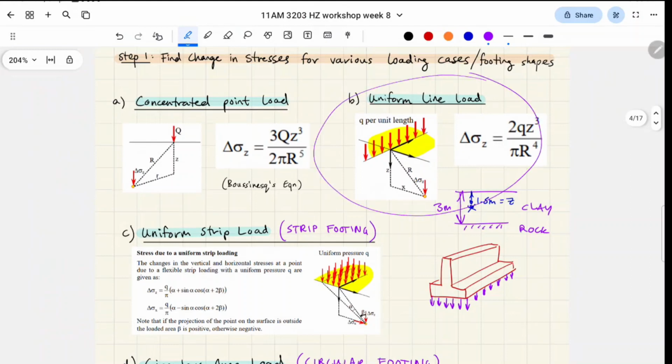Uniform line loads are similar to point loads, but acting in a straight line into the page, right? So if this is your soil surface, and then we have whatever footing, let's say, that could be a point load. But going into the page, and it's one-dimensional this way, it's just a one-dimensional distributed load, where it has no width, basically, when we're looking at the cross-section. That's a line load. Got it? All right.